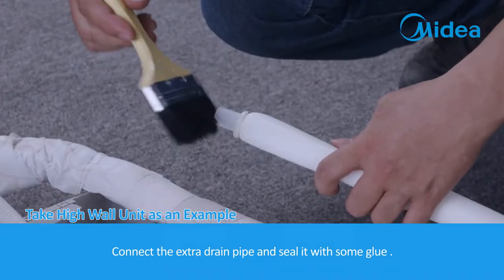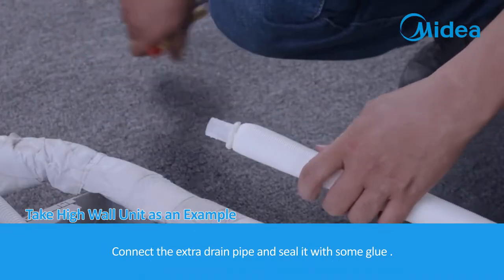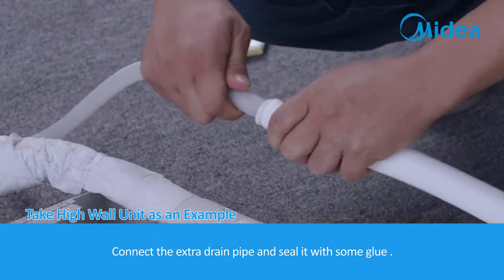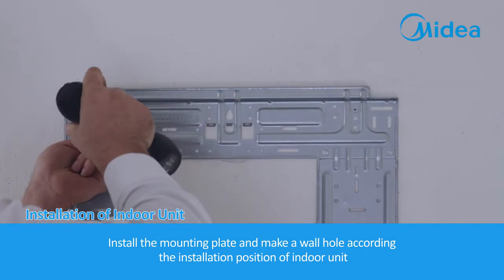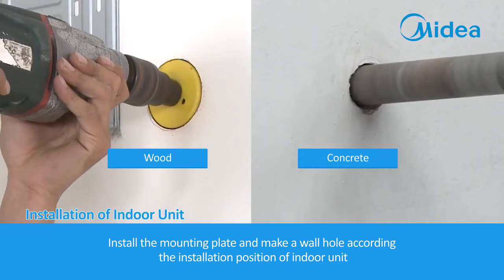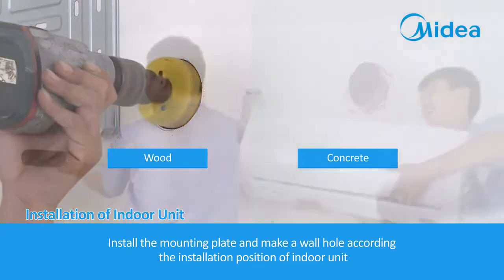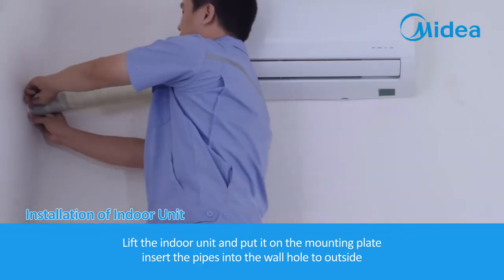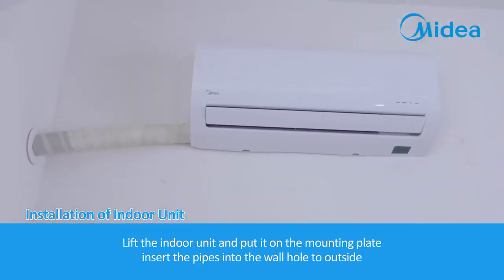Connect the extra drain pipe and seal it with some glue. Install the mounting plate and make a wall hole according to the installation position of indoor unit. Lift the indoor unit and put it on the mounting plate. Insert the pipes into the wall hole to outside.